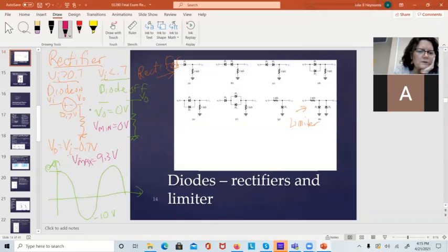So it would follow along pretty much with the sine wave until we got to about there. And every place where Vn was less than 0.7 of a volt, I get 0 out. I get something that looks like this. And this is my V out curve. And the green one is my Vn curve. And I know what the min and the max are.